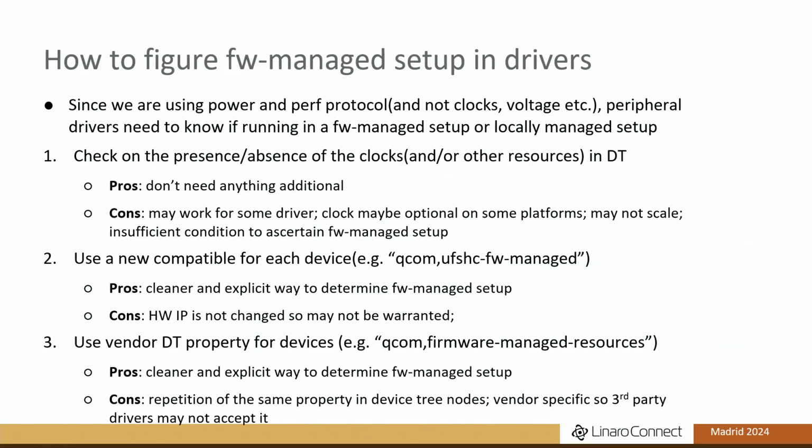Okay, this slide is on the implementation side. If we had to write the driver from scratch, there wouldn't have been any problem in the simplified version, but in Linux we actually modify the existing driver, and that's where the challenge comes, because we are not using clocks and voltage individually. Instead, we are using power and performance protocols. So the peripheral drivers now need to know which variant they are running on.